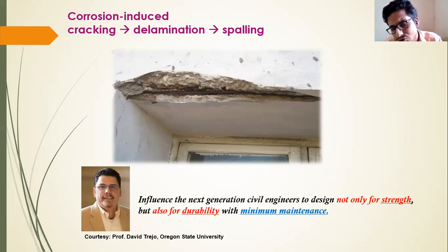Nowadays a lot of admixtures are available, and a lot of processes too. People are replacing cement with different types of materials to improve the strength of the concrete. But improving the strength is not the main thing. The main thing is whether your concrete system is durable or not. Will it last for a long time? This is the question. I have shown you the data: within 10 years concrete structures are getting distressed. So you have to take care of all those things.